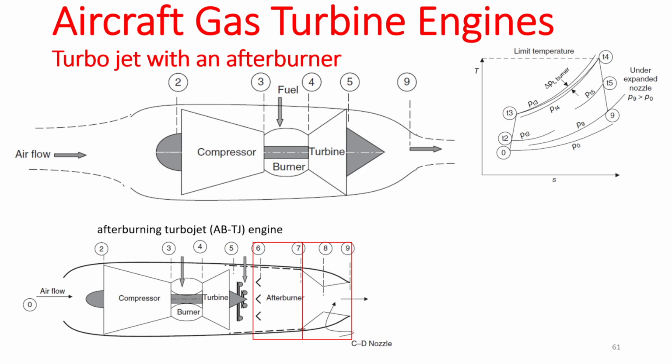Afterburners are mostly used in military applications, mainly because they can actually double the thrust you can get out of the engine, but they will quadruple the amount of fuel you are going to consume. So the fuel consumption is very, very high with the afterburner. Of course, there are ways that you can minimize the fuel consumption, but from a fuel consumption standpoint, using an afterburner is not worth it.